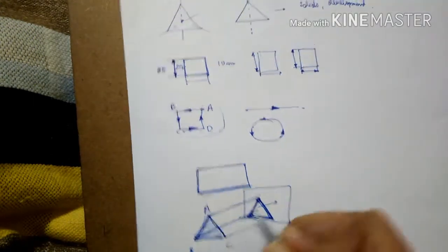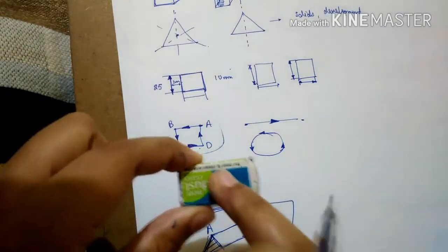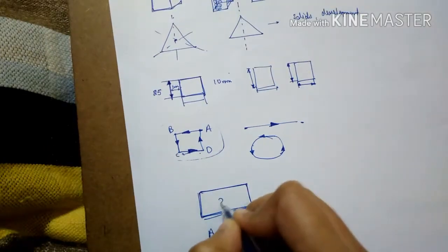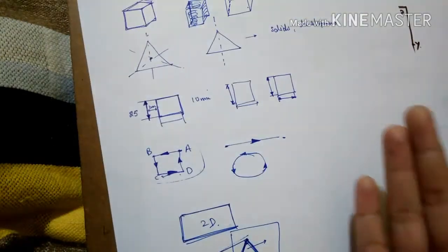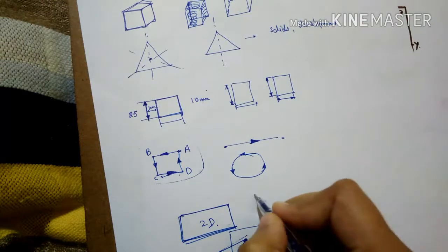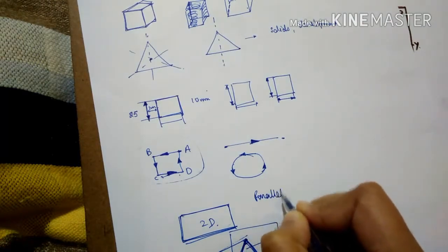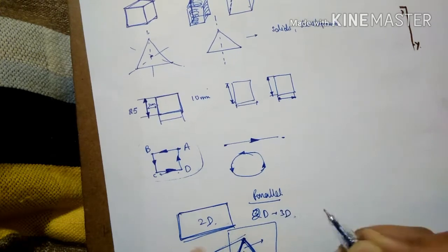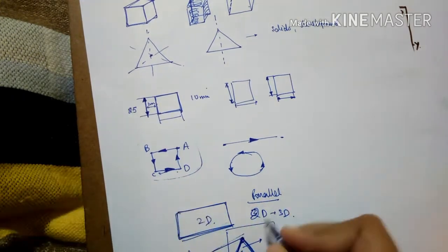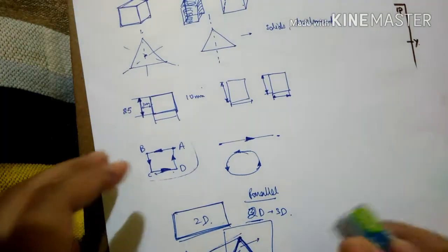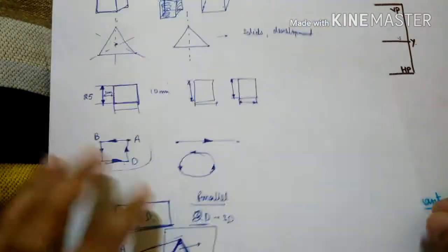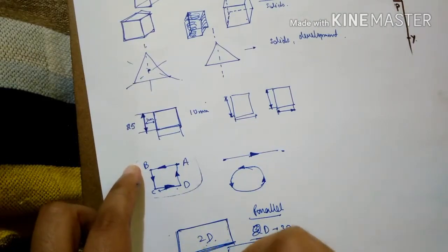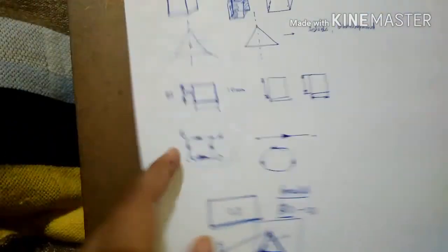So what you had was a 3D object. I had an eraser, I projected the lines and it was a 3D object. But what I am getting is 2D. So what is orthographic projection? You can define it: it's a parallel line projection where we obtain a 2D image of a 3D object, a way of representing a 3D object in a 2D plane. In parallel line projection, because the light rays are parallel, the image will always be the same size as the object. There will be no change.